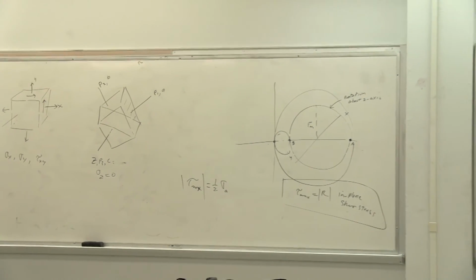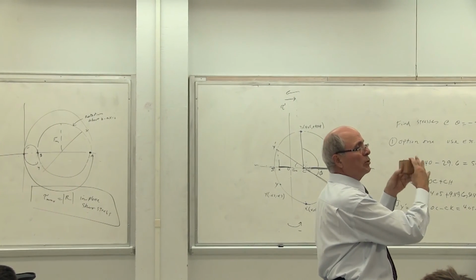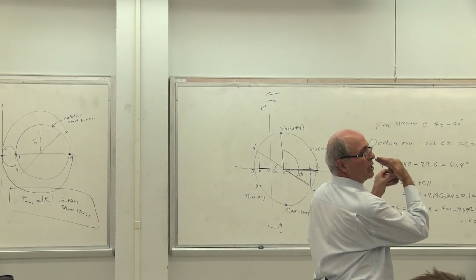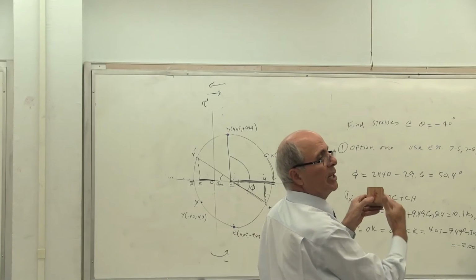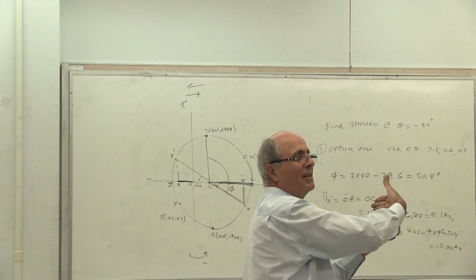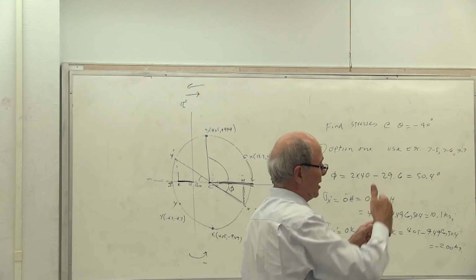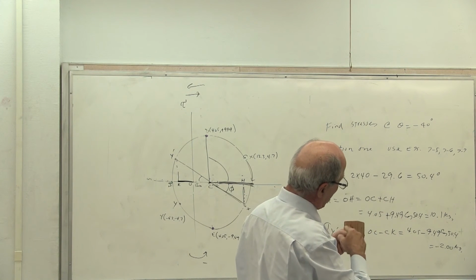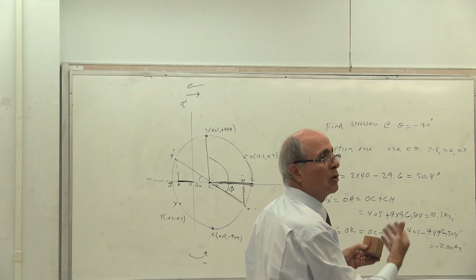This is the original state of stress. Yes or no? You rotate it this way or the other way to get to the principal stresses. If I go this way, this is rotation about the z-axis. This is 45 degrees. The shear is here. Everybody understands. However, I can do this. Where is this shear? This is the shear about the rotation about the y-axis. And the other one that goes perhaps from, there is one more there. One more there, rotation about this axis. Everybody understands. So we have 3 of them.